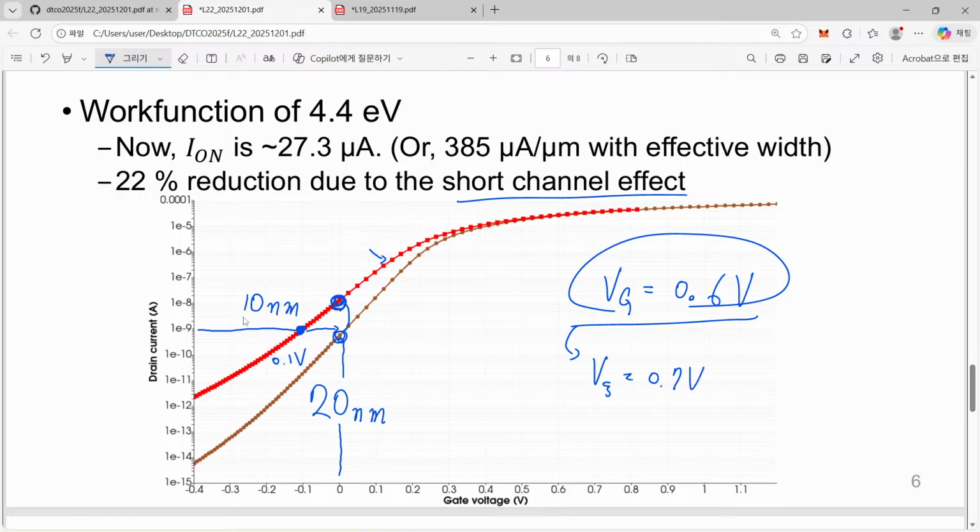So now you understand the importance of this off current matching. According to this procedure, if your off current is too high, then the gate voltage we use in our calculation is much reduced from our correct VDD value.